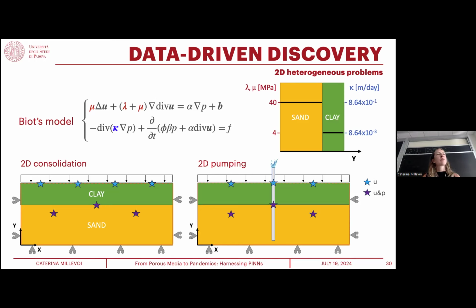The values of the gradients that you apply to the weights and to the parameters maybe are similar, but the scale at which the weights are is really different from the scale at which the parameters are. For example, maybe the weights of the neural networks are on the scale of 10 to the minus 5, while the parameters are megapascal, 10 to the power of 5. Do you rescale the gradients or the parameters?